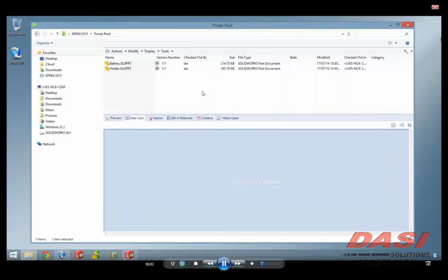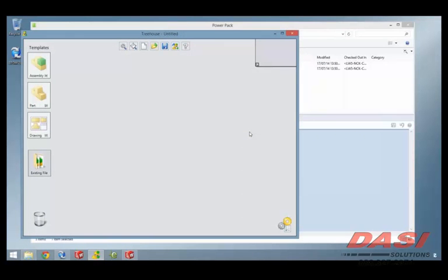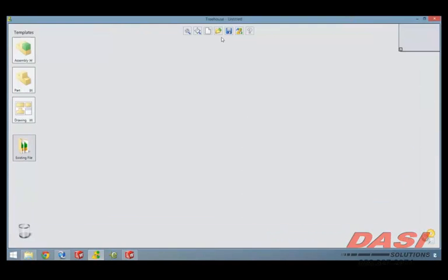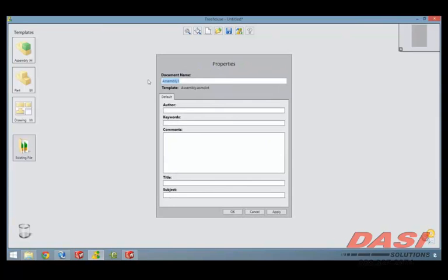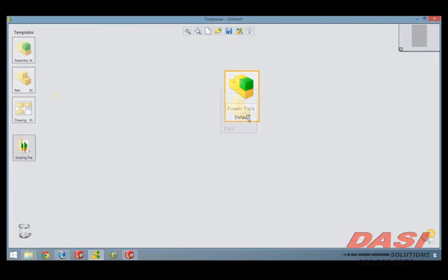So when we've got these product structures predefined, what we can do is actually use this new tool. It's actually an old tool. It's part of our SolidWorks Labs capabilities, but it's a new tool called Treehouse. Treehouse allows us to go ahead and predefine by dragging assemblies and parts and structuring them together. Now, these are based on property templates, so the properties are the same as they would be as you're starting a brand new SolidWorks file.